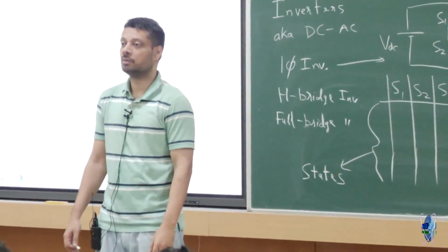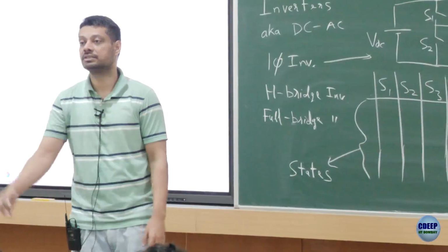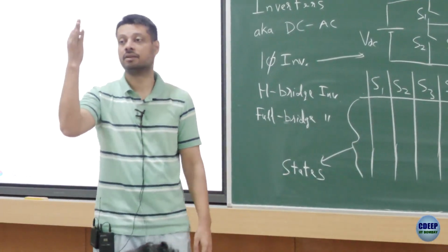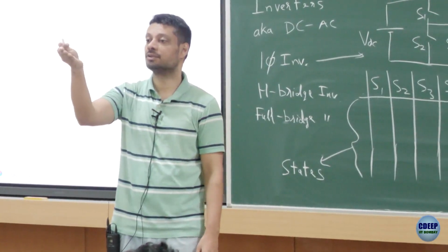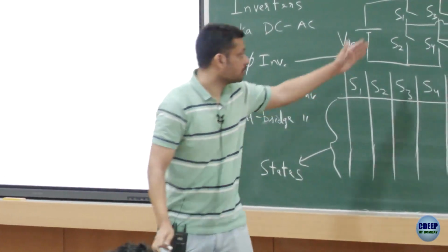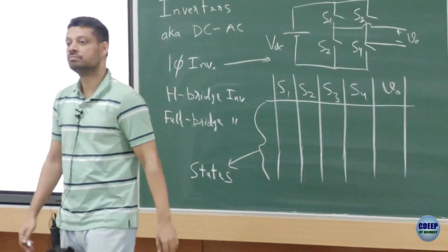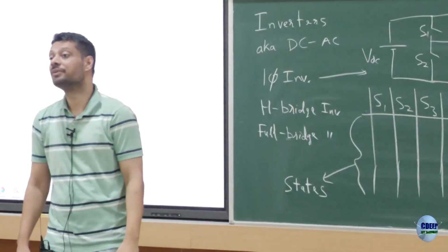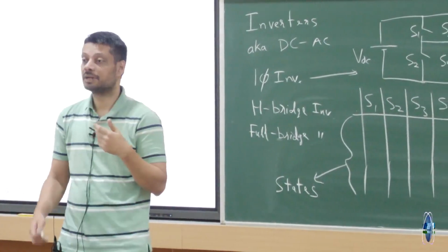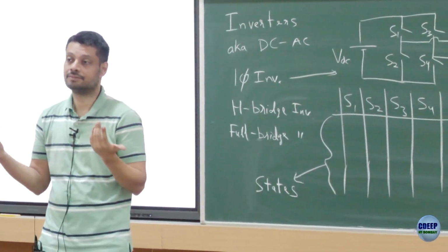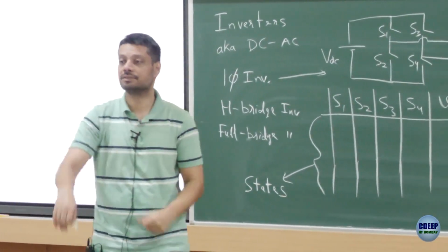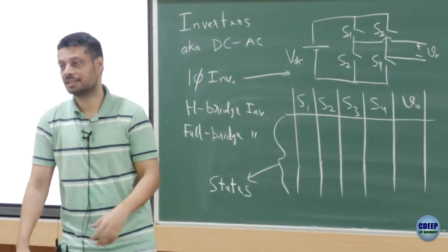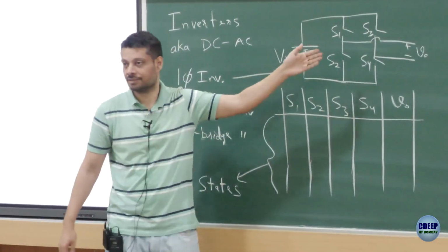Right? Why do you eliminate those states? Anyone from the back? Why can't I turn on both S1 and S2? Why don't you turn on S1 and S2? That will be a short circuit, right? Your DC will be short circuited.